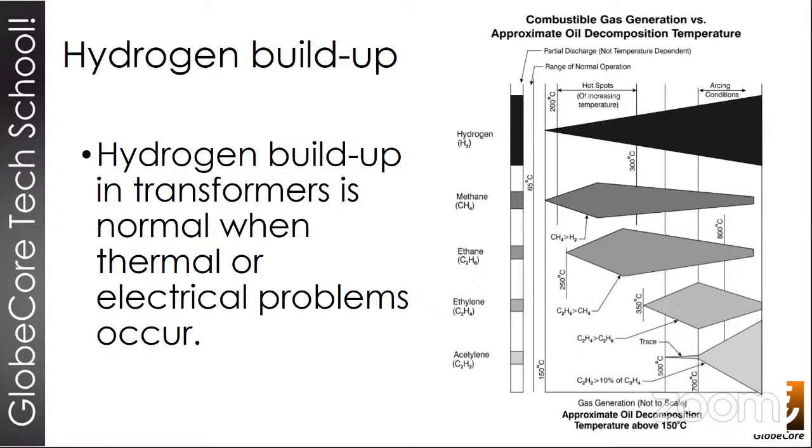So this is why there is a series of sensors that only monitor hydrogen level. And this allows us to know if there is a change in the operation of the transformers. And it's also usually one of the highest concentrations in chromatographic studies. So knowing the amount of hydrogen in oil is a very good indicator for determining the efficiency of our thermovacuum processes and our degassing processes.